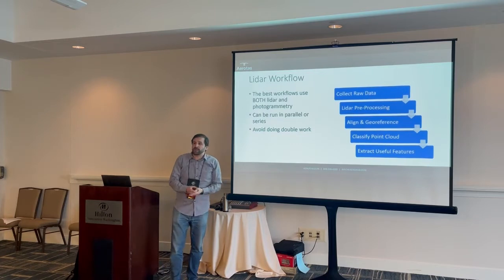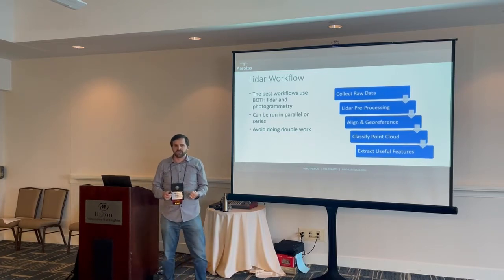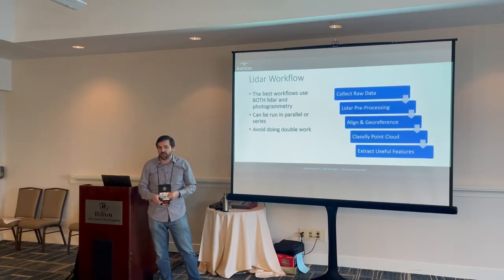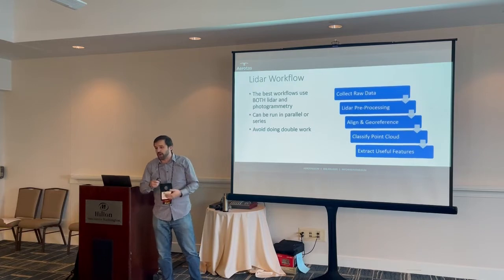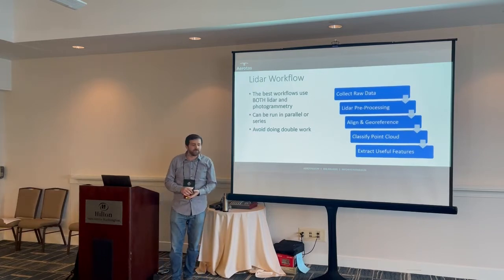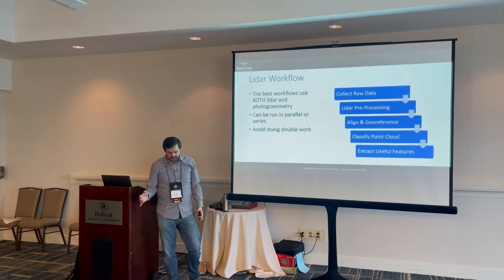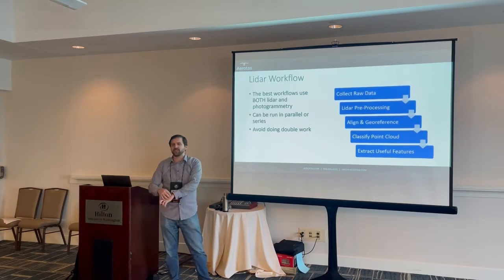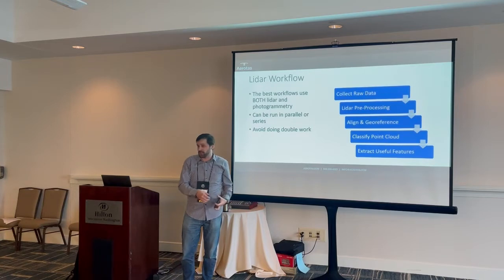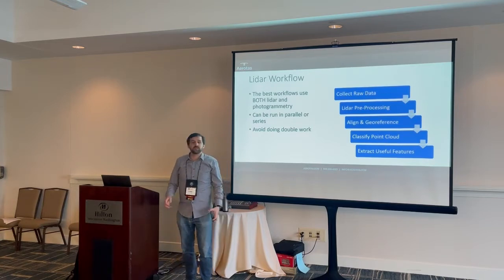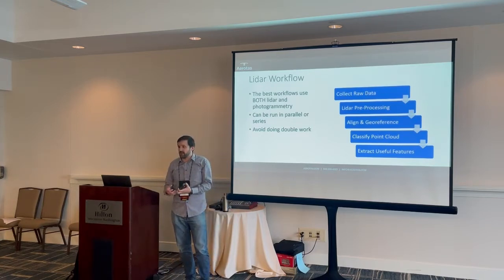Going through LiDAR pre-processing. LiDAR pre-processing is actually a very important step, and one that, if you haven't done it before, is easy to think is just automatic. LiDAR pre-processing is the step of taking the raw data from the drone and turning it into a point cloud, into an LAS file. The drones themselves don't actually create LAS files. They don't create point clouds automatically.